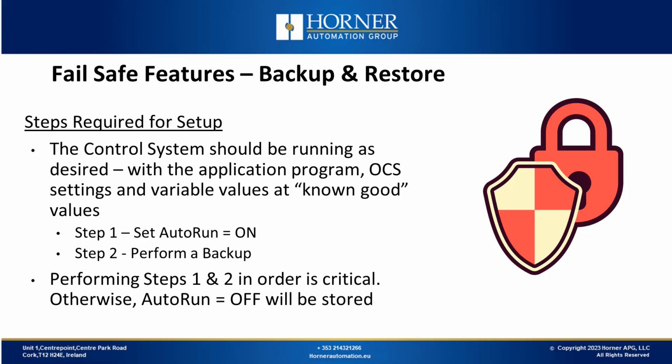Step 1 is to set auto run equals on, and step 2 is to perform a backup. Performing these steps in order is critical. Otherwise, auto run equals off will be stored.